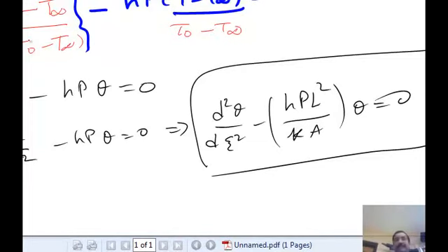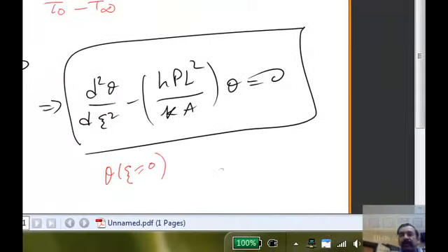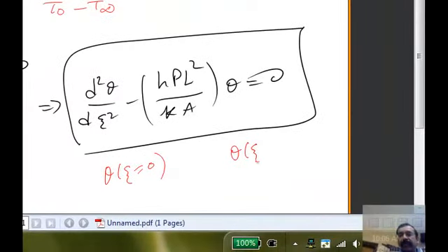Any questions? Now, you need to help me with the boundary conditions. I have transformed the differential equation from T, x to theta, psi. The reason I did that is theta is now going to scale between 0 and 1, and psi is going to scale between 0 and 1. Okay, I won't have huge numbers in MATLAB when I go to MATLAB. So you should be able to do this in an exam, scaling so that you prepare it for MATLAB. What are the boundary conditions in terms of theta at psi equal to 0 and theta at psi equal to 1?